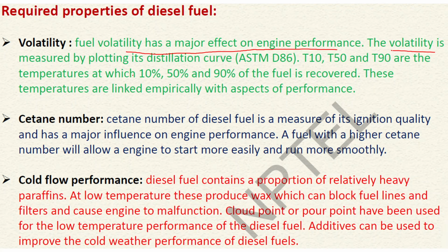The volatility is measured by plotting a distillation curve, that is the ASTM D86 curve, and the diesel fuel should have good volatility, so that, as I told, the diesel vapor mixes with air and combusts in the diesel engine. If there is not sufficient volatility of the diesel fuel, then the vapors will not be generated, and there will be no combustion inside the diesel engine.